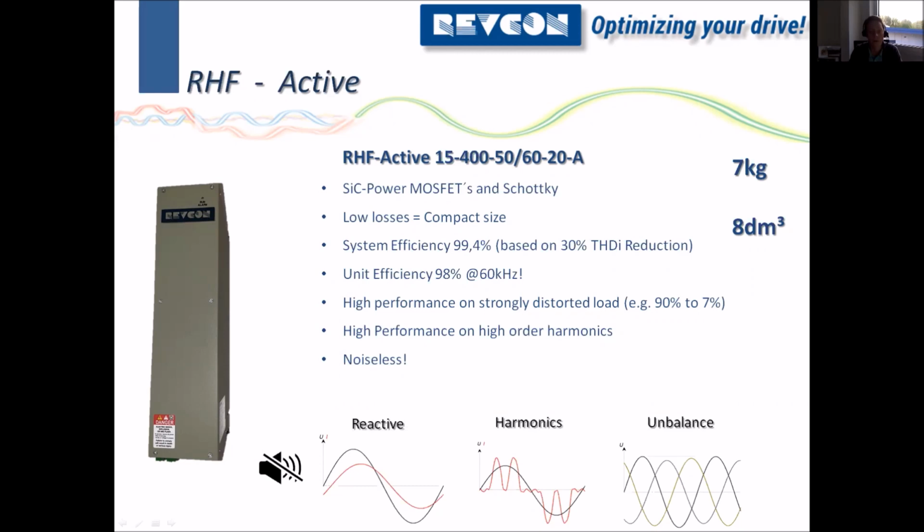No other drive is even close to this efficient, and no other harmonic solution is close to this silicon carbide solution. As a small benefit, it's switching with 60 kilohertz, which means you cannot hear it anymore. So it's completely noiseless. You can solve reactive current, harmonics and unbalance, as with any active harmonic filter, to be fair. But the main benefit of this kind of high switching device is that the accuracy of the elimination of harmonics is much more accurate.